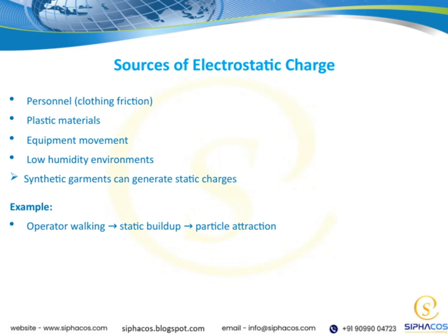Additionally, synthetic garments are notorious for generating static charges. Wearing these types of clothing can increase the likelihood of static accumulation, which is why managing clothing choices can be important in sensitive environments. Overall, understanding these sources helps us better control static buildup and prevent potential issues, especially in settings where static discharge could cause hazards or damage.